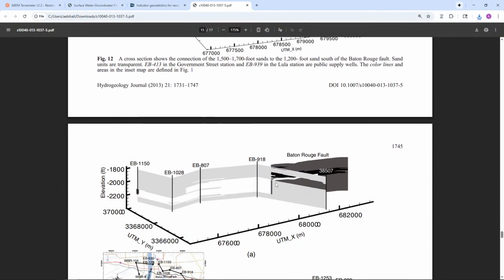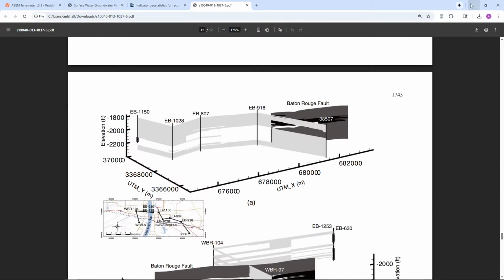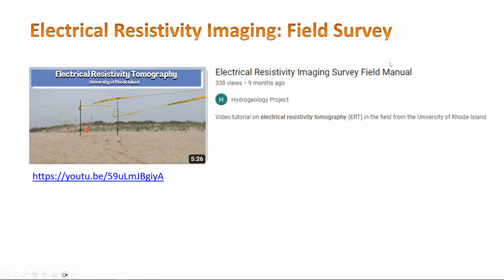You see, just a very narrow preferential flow path. This white is sand, where water flows, and the gray color is clay, where water does not flow. So water just flows here, and it will go and contaminate this one. So we're able to plot preferential flow paths and show how this well got contaminated, for example with saline water, how we salinized this one. Okay, so that's what you get from this type of analysis.